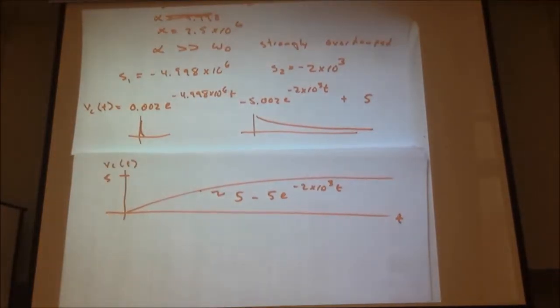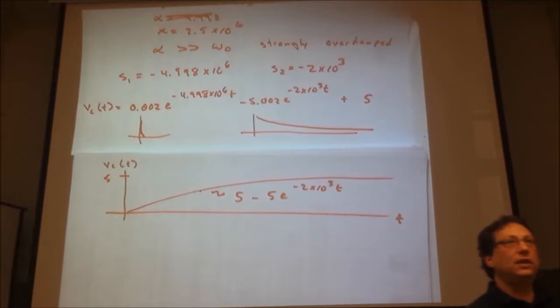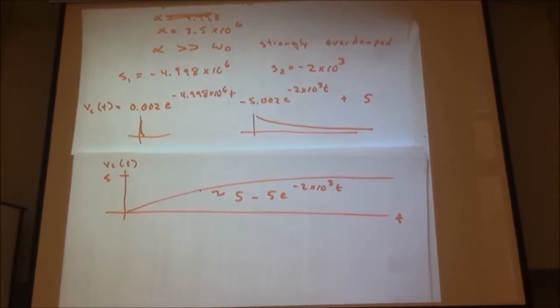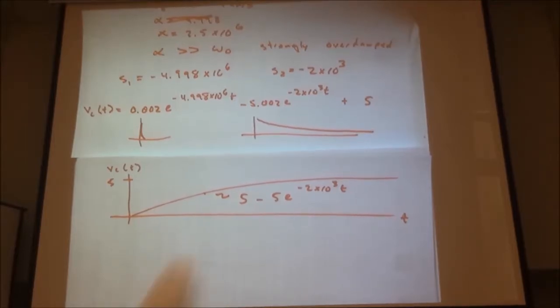So when you get some characteristic response that's second order but strongly overdamped, it behaves like a first order circuit. And from that first order expression, you can do the same analysis that we did in earlier lectures, where you looked at the plot and found the RC time constant. Well, the RC time constant is essentially 1 over alpha, 1 over s in this case. So you can find that directly from the curve as well.